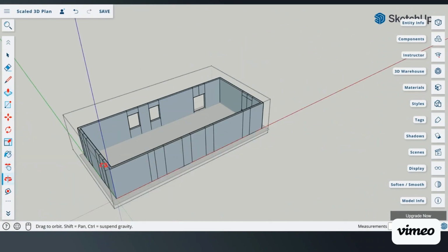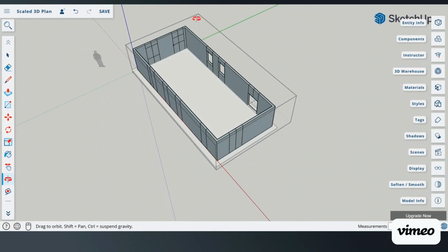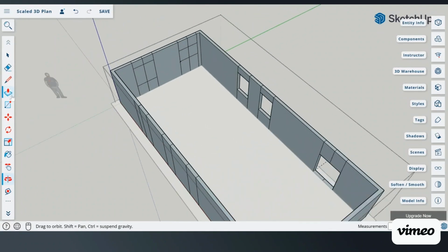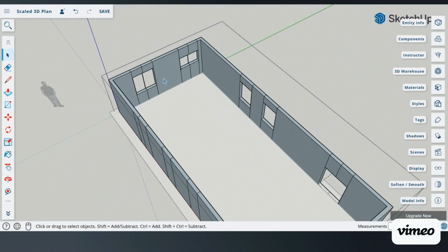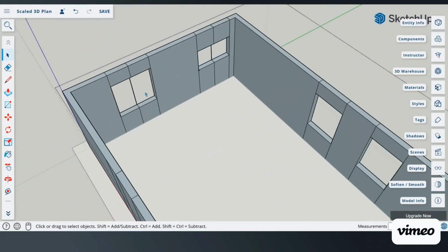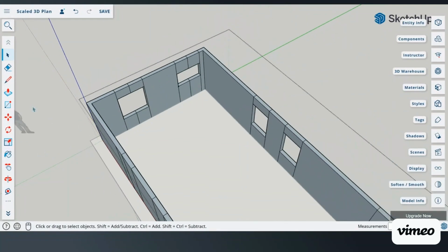And moving your drawing around using your orbit tool, you're just going to go through and continue to push out all of your openings. If you have to, go through and also delete your faces. If you want to delete more than one face, of course you can use your shift key by pressing and holding it down. You can also go through and be sure to remove any of the double lines.